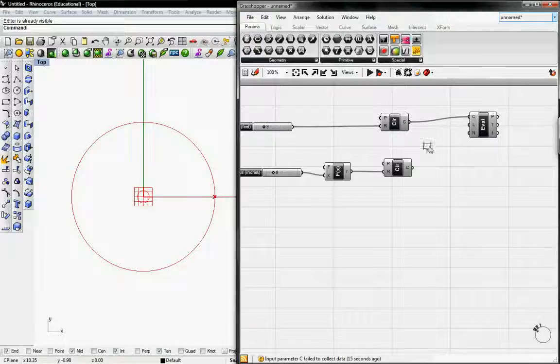If we grab a number slider, which is 0.25 by default, and connect it to L, the length, the point moves from here to here, which is a quarter of a turn, 0.25 of 1. If we push it to 0.5, the point should move halfway around the circle. So if we need random points around the circle, it all needs to be from 0 to 1.